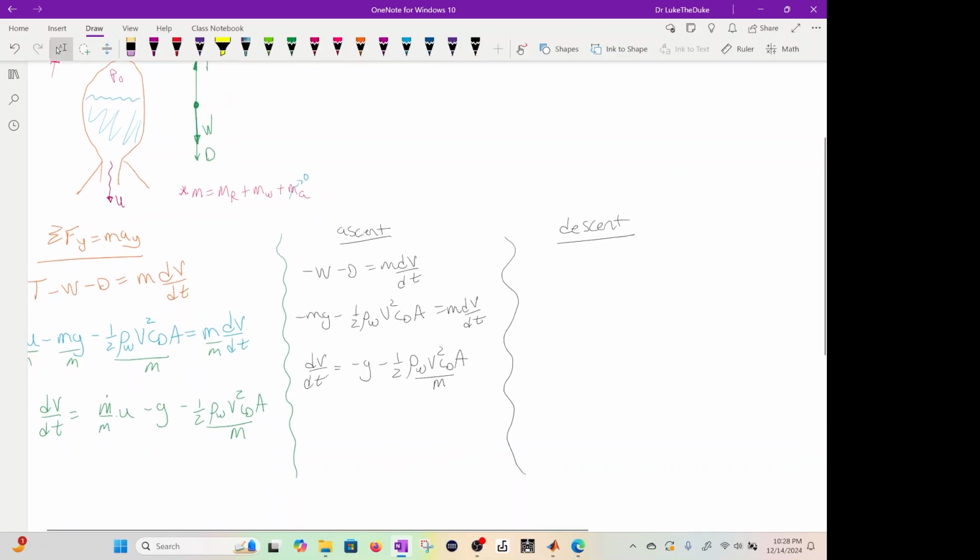Now, for this one, I'll draw the free body diagram up here, and I'll just do it as a simple rocket. Let me erase those. There we go. That is a terrible rocket, Dr. Craig. So here, downward is positive, and we have drag and weight, so W minus D equals m dv/dt, because we want to make sure acceleration is in the positive direction.